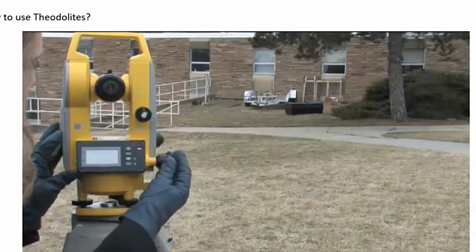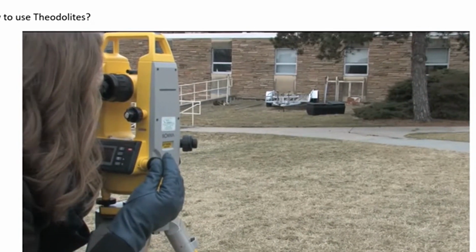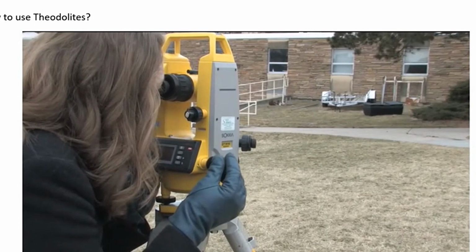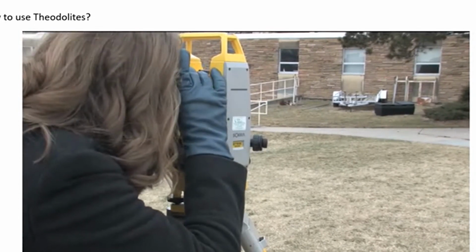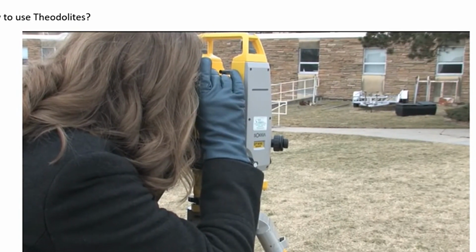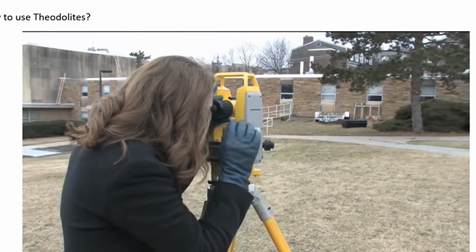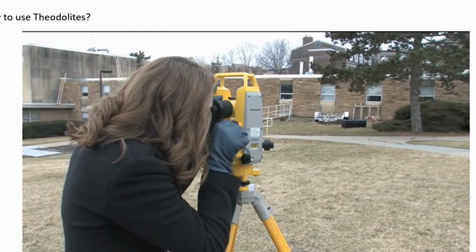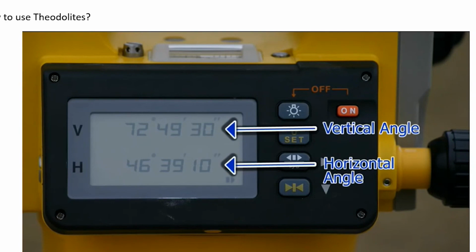Next, we will proceed to turn the angle to the right by unlocking the horizontal and vertical locks and then rotating the scope to be directed towards the rod at point B. At point B, we will once again focus the scope directly on the HI. Once the scope is focused on the HI, rotate the horizontal and vertical locks and use the fine adjustment knobs as necessary to zero in specifically on the HI as best as possible. Proceed to write in the field book the horizontal and vertical angle readings provided by the instrument. This will be your first unplunged horizontal angle.